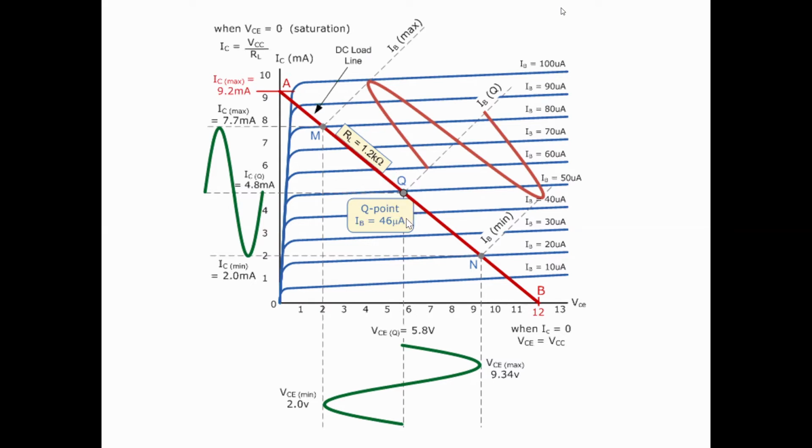And that's why I have to put a capacitor at the beginning and a capacitor bypassing the emitter resistor. That is very, very serious. That is the problem. That's the only problem with transistors. Otherwise, they operate beautifully.